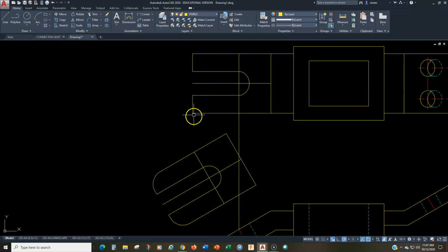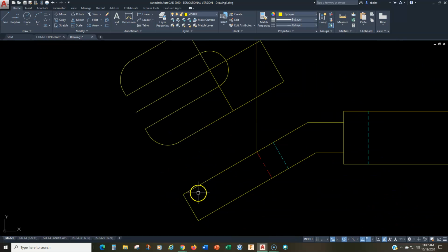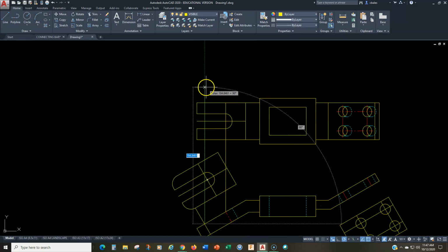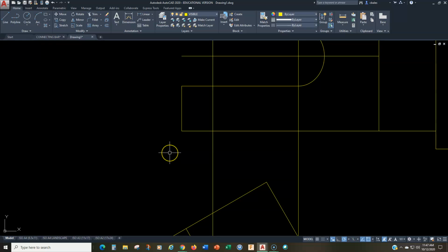Now, for dealing with this one, these outside curves, it gets a little weird, because what we need to do is we need to find where that curve starts, and where the curve starts is right there. Where is that in the front view? Well, we project that back perpendicular to that, and now I'm going to project this up into this space. So we'll go right there. The radius on that is 12, so we're going to offset 12 from here to here. So remember, that doesn't change, but the ellipse does. So from right here to here.